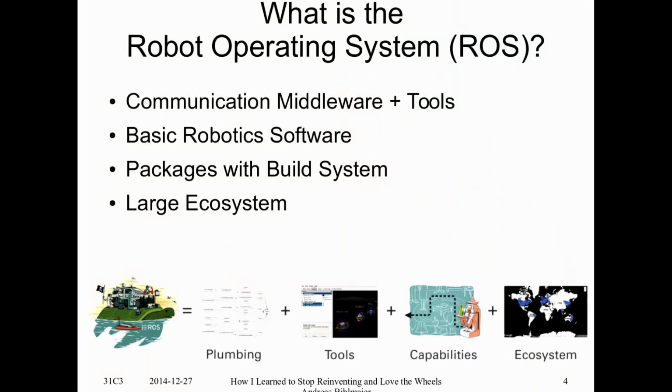So for example, if you have your robot and you want to tell it, move 5 centimeters to the left, you usually specify that within some kind of coordinate frame. So either it is the coordinate frame of the robot, or the coordinate frame of my laptop, and so on. And in the background you do just some matrix multiplications to get everything right. Perhaps you remember your algebra classes or not. It does not matter, because here it's just an API call. Give me this position in this coordinate frame, and it will do all the magic algebra in the background.